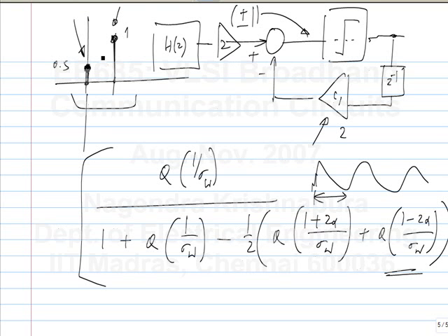So the reason why I keep saying something is the cursor, where it's a relatively arbitrary treatment, is that you would like this to contribute to the signal and you cancel the remaining intersymbol interference terms. You can also do the other way. You can retain this and cancel off this. In that case, you will have worse performance because you are treating the smaller one as signal. So for the same amount of added noise, you will have a lower signal to noise ratio or a higher bit error rate. Okay. Is this clear? I think you asked about this, right?